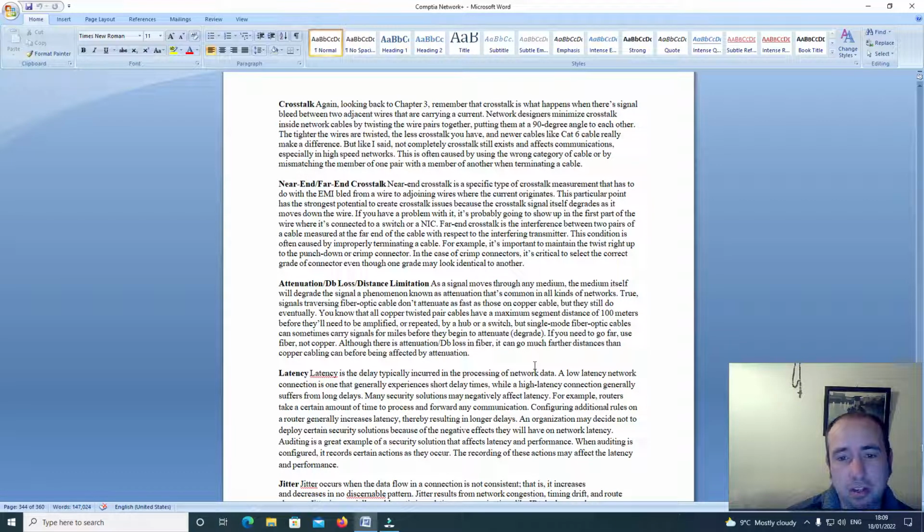Crosstalk still exists and affects communication, especially in high-speed networks. This is often caused by using the wrong category of cable or by mismatching the member of one pair with a member of another when terminating a cable.